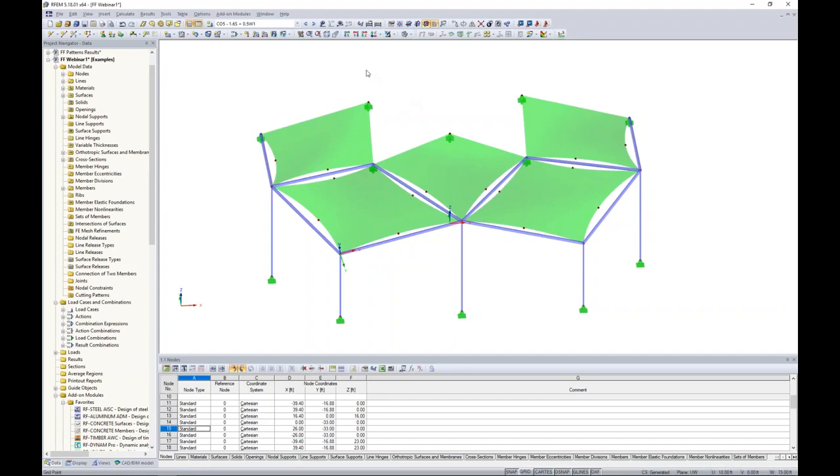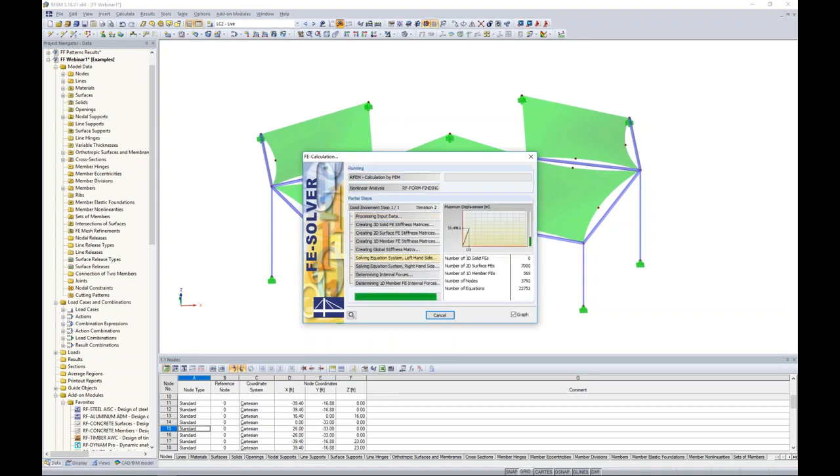Well, what I want to do here is to jump to only my live load case, and I'm going to go ahead and apply the live load case only to the structure. Now remember, we lost our form finding results previously because I said, well, I want to include self-weight now. So we're now including self-weight. The program needs to run back through that form finding procedure. Then we're applying the downward load for live load.